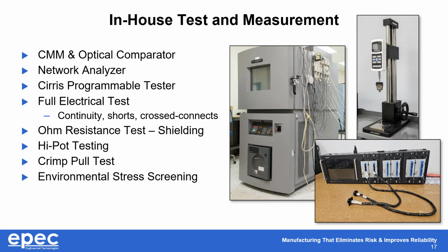Lastly, and most importantly, we have a full line of environmental test chambers here at Epic that we can use once we have a reverse engineered item built. We can stress it and subject it to high temperatures, low temperatures, and even thermal shock through temperature cycling to go and make sure that our replacement item will meet the requirements that you're trying to solve.